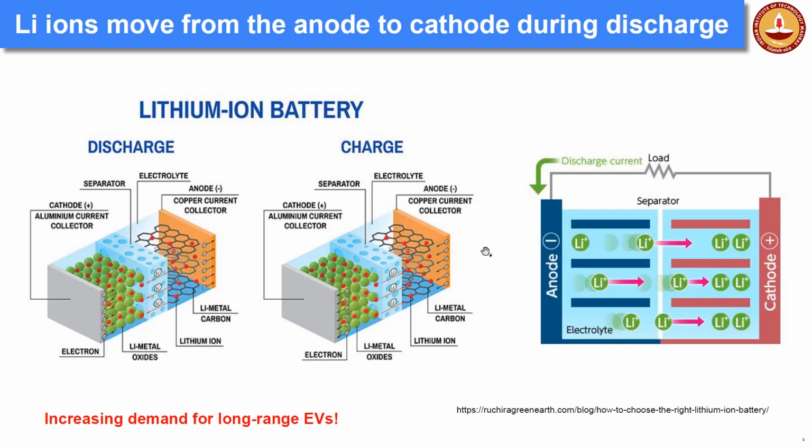Okay, so in between, whatever we are seeing, there will be some electrolyte like ethylene carbonate, propylene carbonate and so on. They are just solvent molecules essentially, through which this lithium ion will be traveling and reaching the other end, where the anode is graphite. You all might be knowing the structure. Here you can also see this honeycomb type structure, the stacked layers of graphene. These are nothing but the graphite. Here the red dots correspond to the places where the lithium atoms will be going and absorbing onto the surface. And once you stop the charging, it will automatically start the discharge, right?